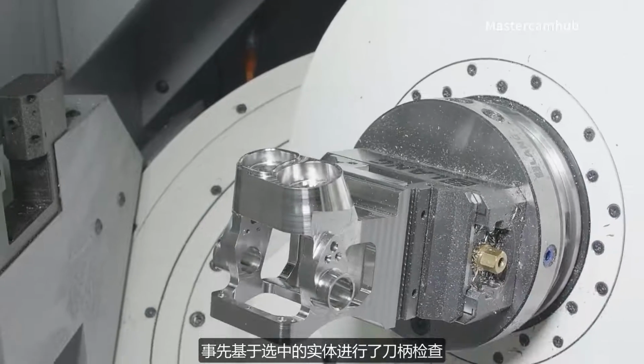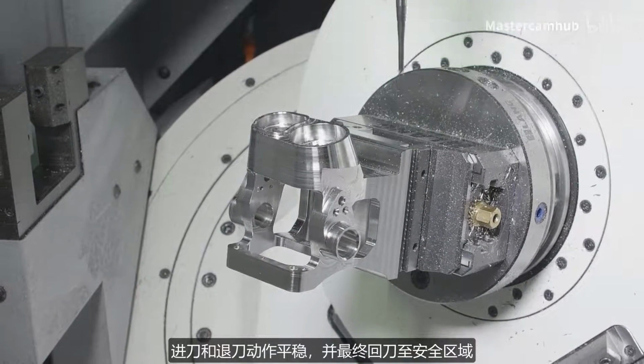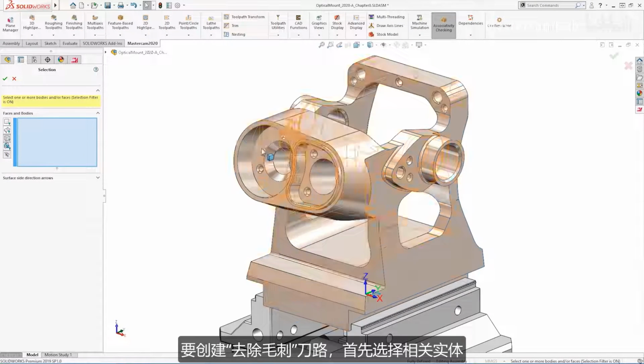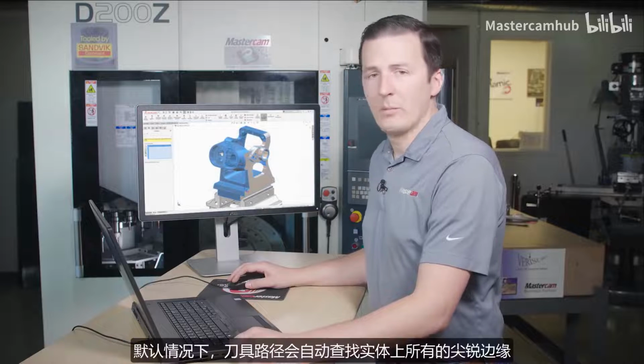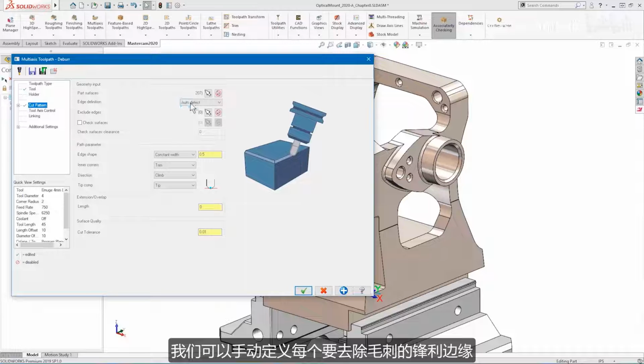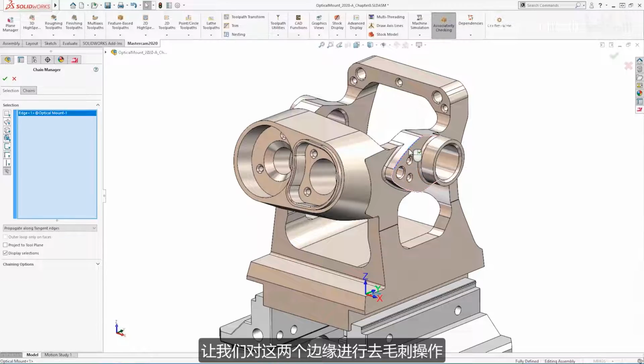The tool holder is collision checked against the solid body. There are smooth entry and exit moves, as well as a final safe move to the clearance area. To create a deburr toolpath, we first select the solid body. By default, the toolpath will find all sharp edges on the body. We can then select some edges to avoid. The alternative option lets us manually define each sharp edge to be deburred. Let's deburr these 2 edges.